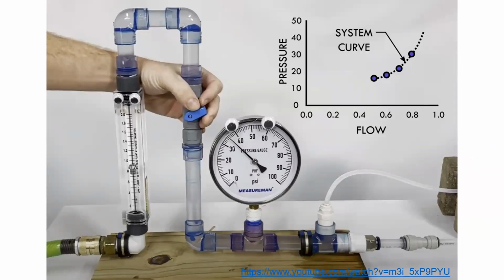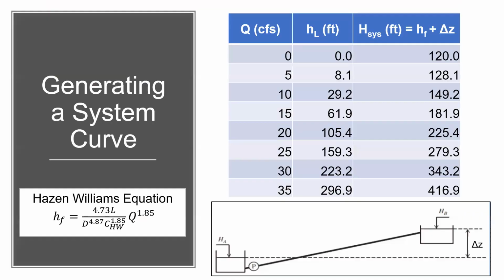Let's talk about system curves, and then we'll actually do a system curve calculation. In the video we watched previously, we looked at how a system curve might be generated just from measurements. So at different flow rates, what's the pressure in the system? And that's the pressure essentially that the pump would be pushing against. So this is a flow meter, here's a pressure gauge, and you can create a system curve that way. But we don't necessarily have this kind of equipment or scenarios to run on a system, so we can refer to calculations.